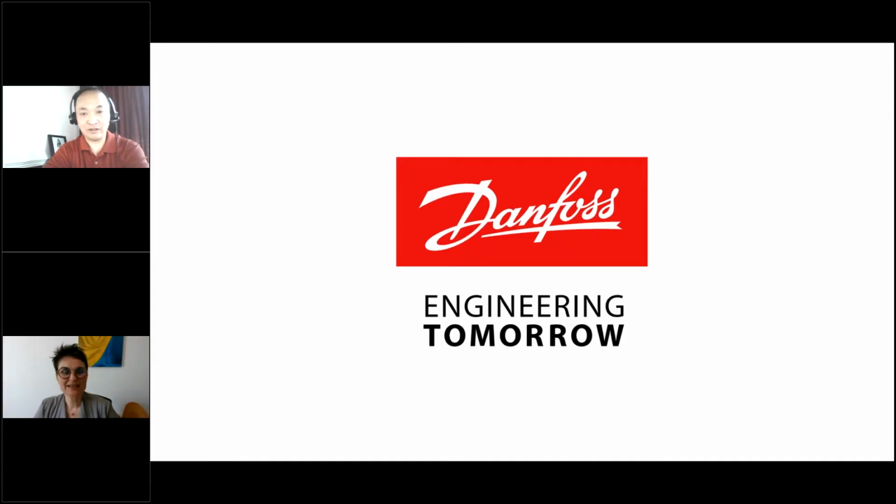Yes, that's a good point. The key feature that we're trying to emphasize here, which is a recent enhancement, is the addition of the high SST capability to our TT and TG line of compressors. For those compressors, we can reach a maximum of 28 C saturated suction temperature. Now, there are going to be some compressors, depending on the operating condition, that can get maybe a little bit higher, because it really all depends. It is a function of your operating conditions, your load conditions, etc. But in general, you should be able to see 28 degrees Celsius capability.